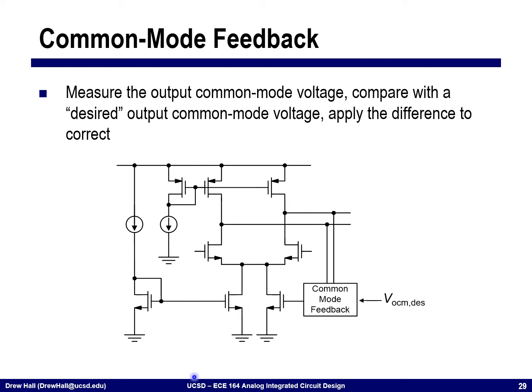Okay? And importantly, this occurs because I have essentially what looks like two current sources. I have this PMOS current source and I have this NMOS current source with a very ill-defined voltage in the middle. It's only really after I consider second order effects of the output impedance in the DC biasing calculation that we can figure out what this Vout node is. Okay? And so this is where this type of feedback can also be used, but for what's called